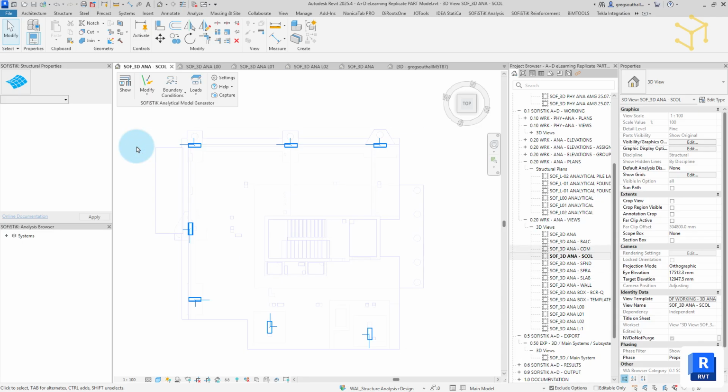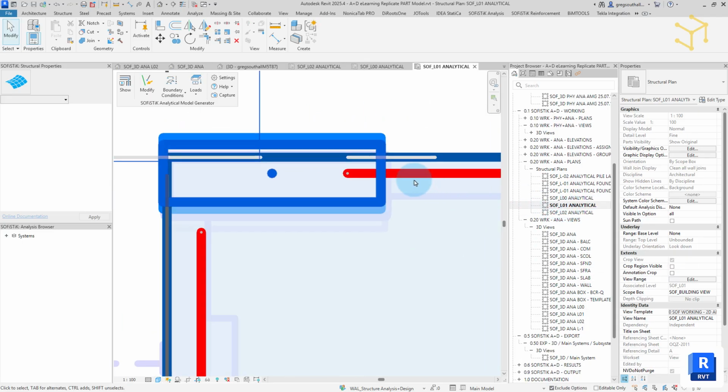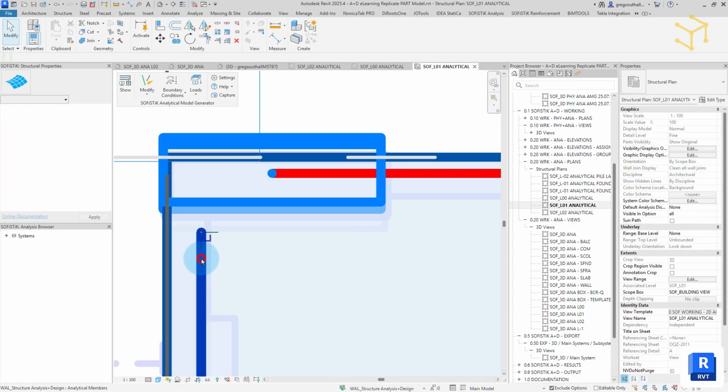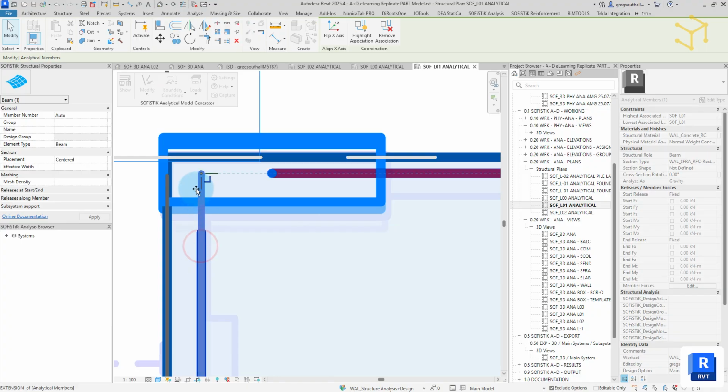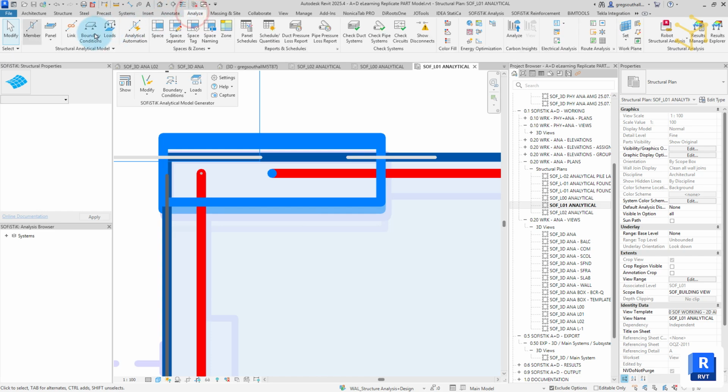Once the adjustments are made, we can return to the 2D Level 1 plan and use the grab handles to rejoin the beam ends. Where a beam no longer aligns with the column, we can place an analytical rigid link to provide support to the beam end.